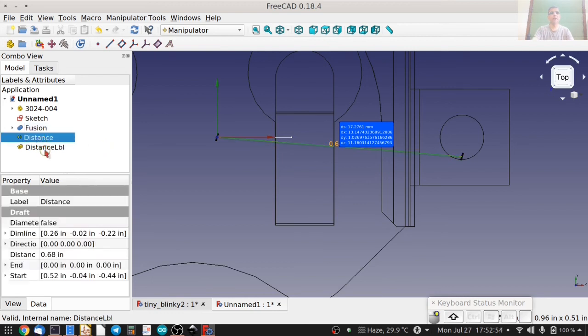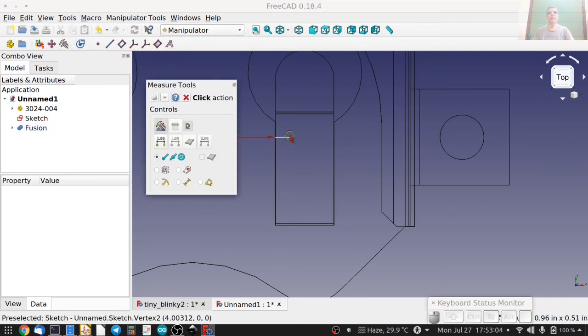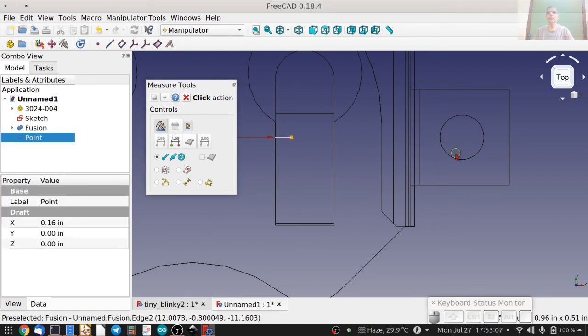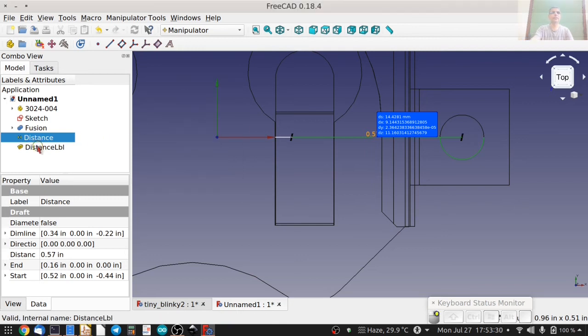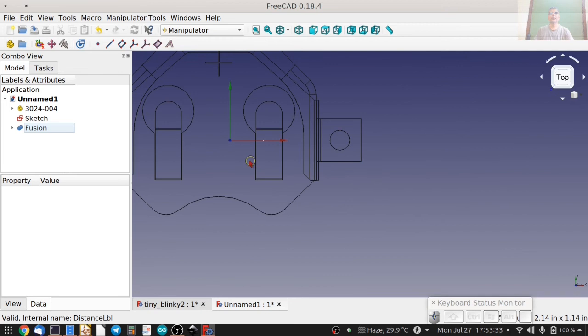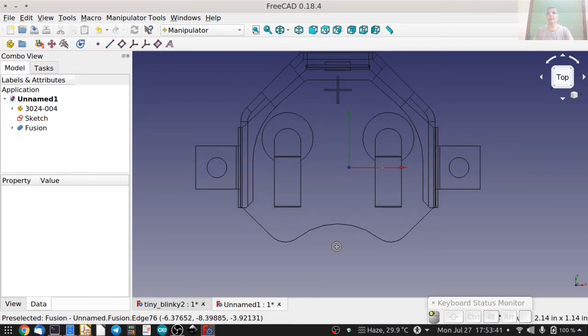So we can now remove these two labels, and just to verify, let's go back to manipulator, click on caliper. We can select this endpoint and this circle, and we can see that dy is now a pretty small number raised to -0.5. So maybe that's a rounding off error. So we can close measure again, get rid of these labels. So we have things aligned along the y-axis. Let's see if we can get the same thing done along the x-axis.